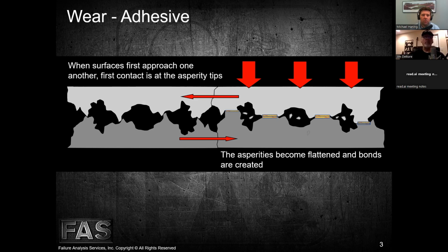So essentially, if we wipe or generate adhesive wear in a crankshaft bearing, the crankshaft is much harder than the bearing, so the bearing material wears away and deposits itself on the crankshaft, and then also a lot of that material flows out with the oil flow as it's released and into the sump or into the filter. So that's kind of how adhesive wear happens: we're generating considerable frictional heat between sliding surfaces. And this can happen with or without lubrication.